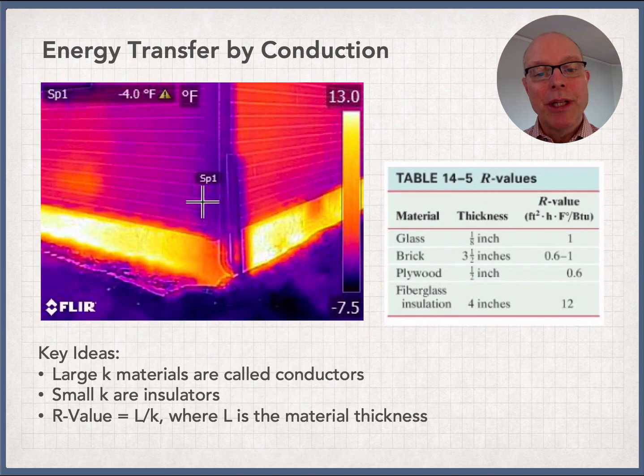This is an example of heat bridging in a way that you could study at home. What we're doing here in this image is looking on a very cold day at the outside of a house. What we're going to ask you to do is do exactly that, and also to try the flip side, to go into your basement and look at the sill. So the sill is the wooden plate that your entire house rests on, and if you have an unfinished basement and can get to it, look at it from above, you might see some thermal bridging.